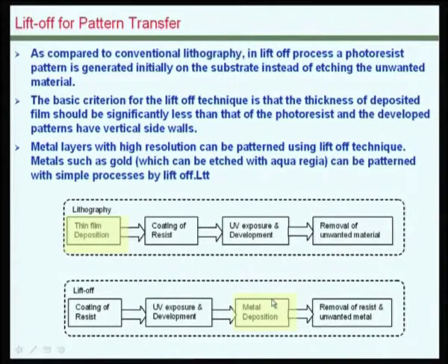Usually metal thin films such as gold are patterned by using Liftoff technique. As you may know, for etching gold usually aqua regia is used, which is a nasty chemical. There are other chemicals that could be used, but still it is usually preferred to go with the Liftoff approach for the accurate patterning of films such as gold.